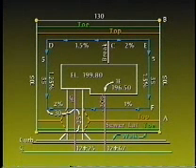The site plan shows the swale as being 5 feet from the house and 25 feet from the back of the walk. With this information, we can determine the distance from our given invert to the back of the walk, which is 28 feet. Next, calculate the invert of the pipe and then the cut to the invert of the pipe. Questions 2, 3, and 5 all require elevations along the swale.